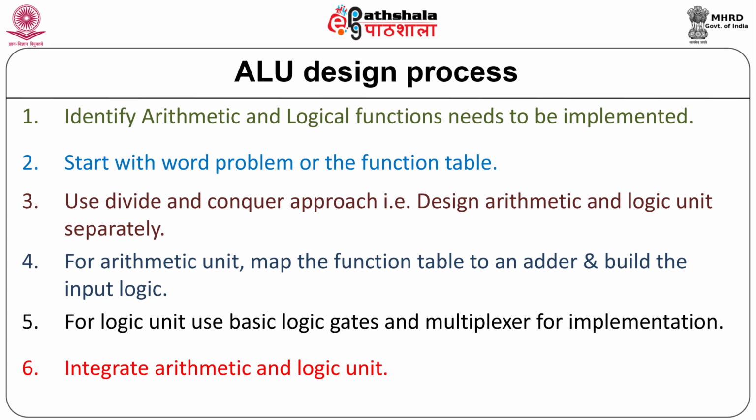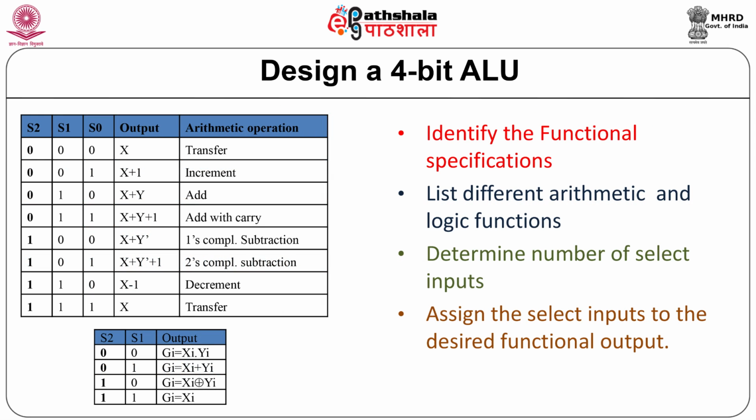Step 4, for arithmetic unit, map the function table to the adder and build the input logic. Step 5, for logic input, use basic logic gates and multiplexer for implementation. And last step, integrate arithmetic and logic unit. Let us now consider a 4-bit ALU design.